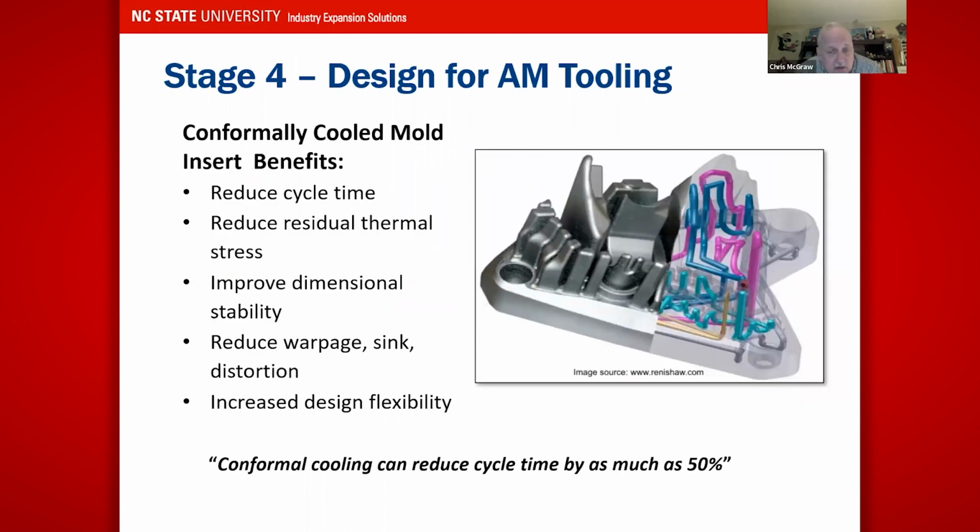A big way this is being used now is in the injection molding world, in that we can cool our inserts, our parts quickly and get cooling where it is needed. One of the things that causes most quality issues in plastics is warpage, shrinkage, and things, because things don't cool at the same rate. If I'm trying to make a part that has a thin flange or something on it, if it cools too quickly, it may bend or warp. Whereas with this, we can get cooling to where we need it to be in the right time.